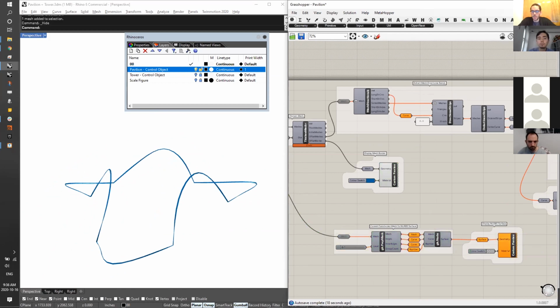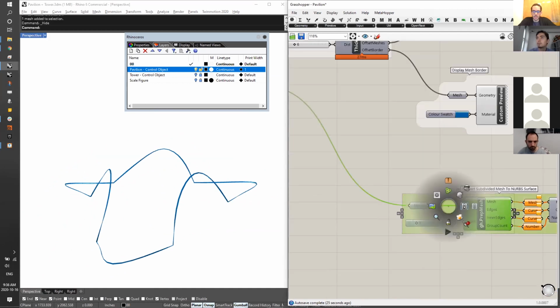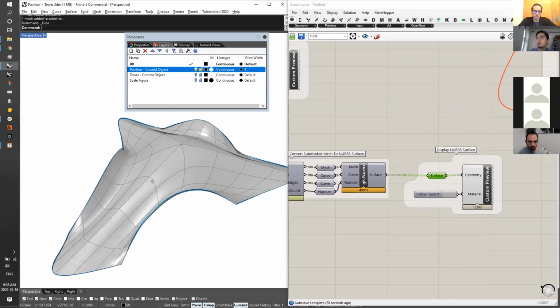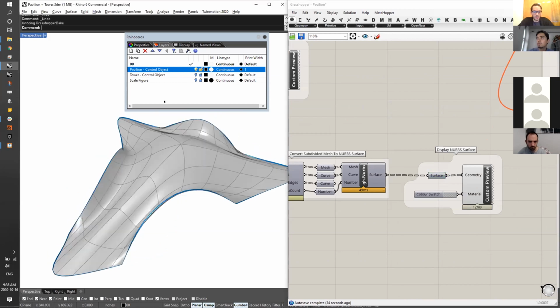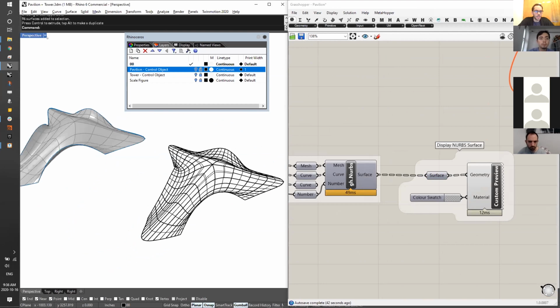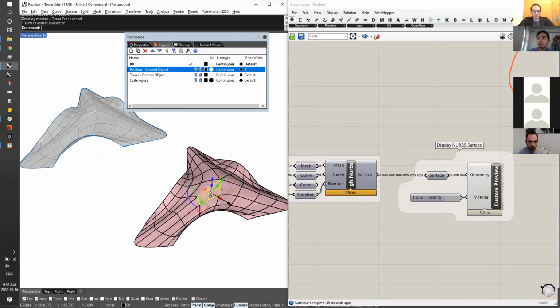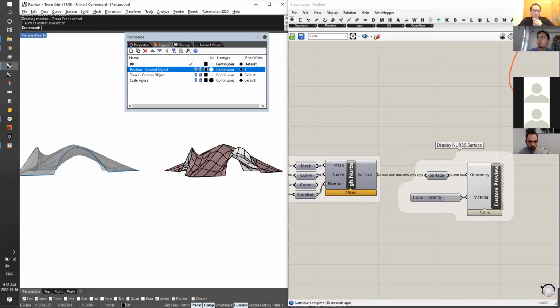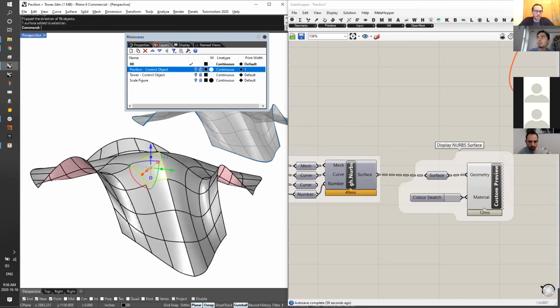So before we dive into the whole concept of directions and whatnot, we are going to dive into the idea of how to reconstruct a clean NURBS surface from a particular mesh object. Now, the only caveat to this is that the NURBS object needs to derive itself from a clean, and when I say clean, a sort of subdivided mesh, right? Because the way the mesh subdivides gives us a level of control and a level of conditions that we can use to reorient and resort the faces and then build a clean NURBS model.